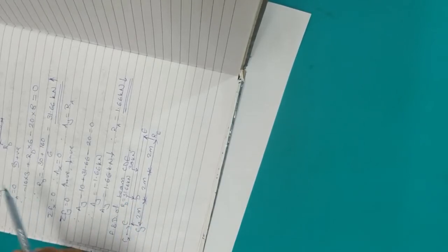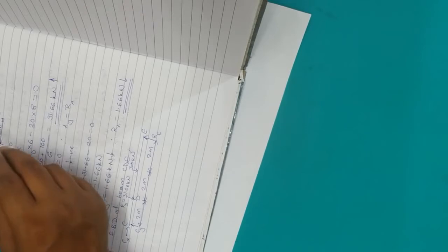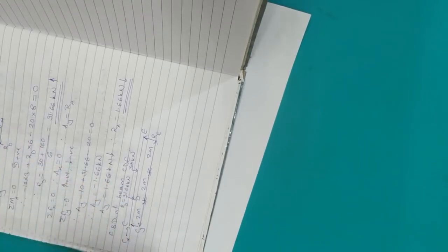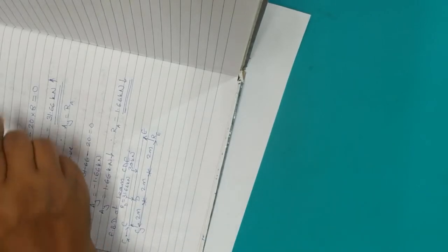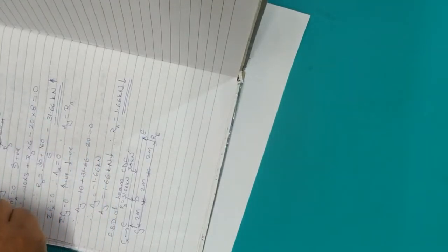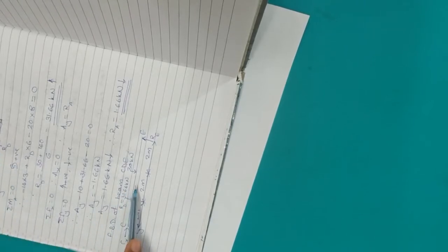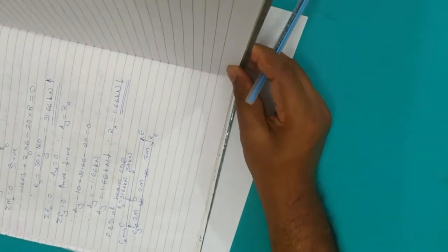So if at all you are going to draw FBD of the entire compound beam as such, you don't have to show the reaction of the roller, because they are going to nullify each other's effect. The reaction coming from up and reaction going in the downward direction. So same magnitude in the opposite direction and on the same line, they always cancel each other's effect. So if you are drawing FBD of the complete structure, the reaction of the roller at point D is going to be 0. But after isolation, as we have done here, we must show the equal magnitudes and the opposite directions of the reaction of the roller at point D. Fine. Moving further, let's see how we can solve this.